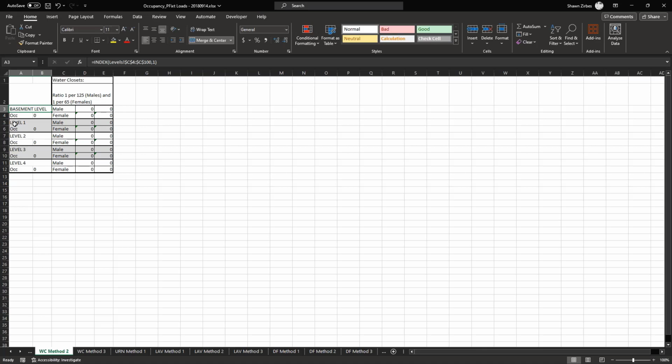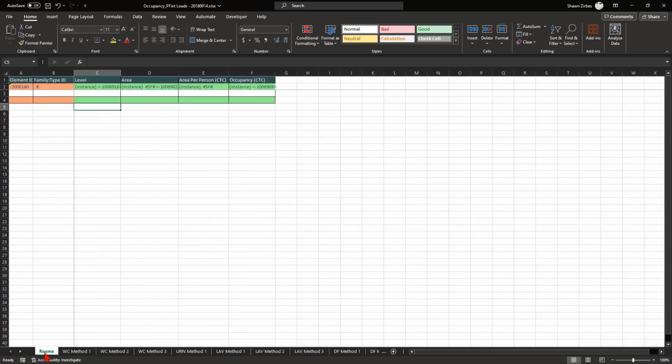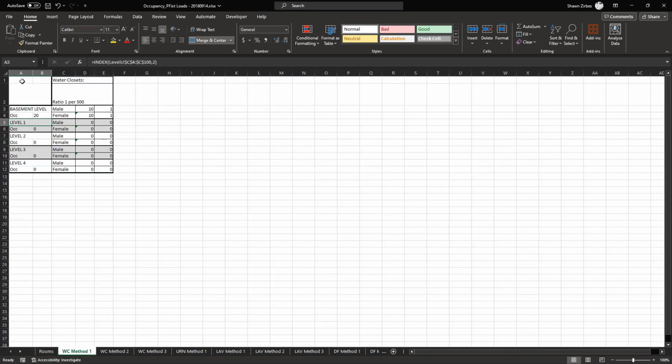The lowest level shows up first, and then the next level, the next level, the next level. If it's a building story, I've got that all pre-populated. So I have Excel spreadsheet tabs that don't know anything about Revit, looking at data that comes out of Revit, like my Rooms tab, via Spreadsheet Link. And now when I populate this with information, these tabs know how to do their calculation, and I'm getting really well formatted items here that match what I need as automatically as I possibly can.